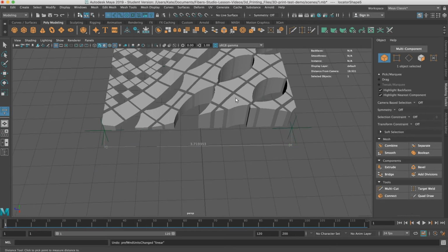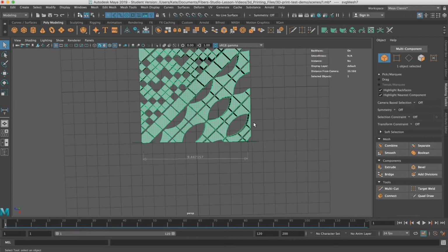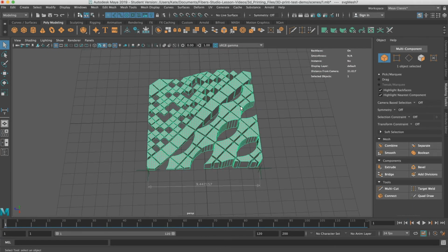Inches. And if you saw, I just exited out of that box, and my distance measurement tool is still open. If you hit Q, it will disable that, so it won't be open anymore. And like you say, this is bigger than 6x6, right? Because it came in differently. So that's what I mean. You have to be careful of the scaling from Illustrator to Maya. Doesn't necessarily translate. Just because you made it this size in Illustrator doesn't mean it's going to be that size in Maya. Although I think if you start with Maya in inches, it will translate better than switching like I did.